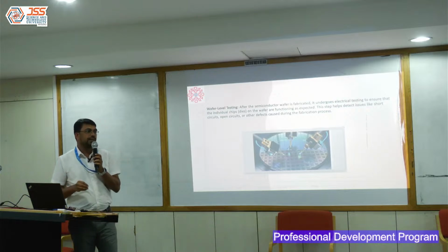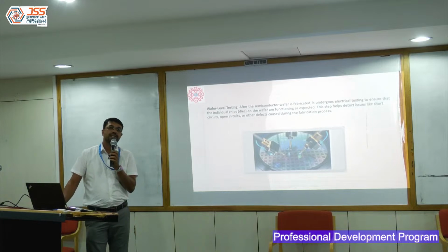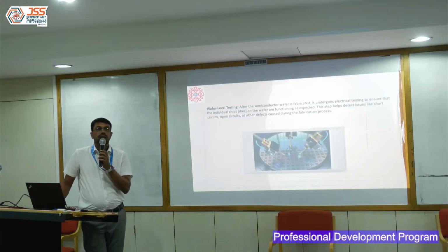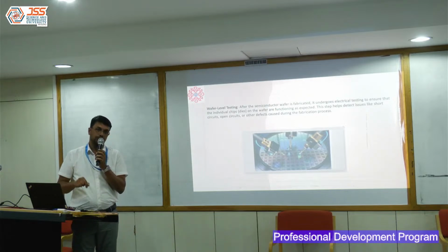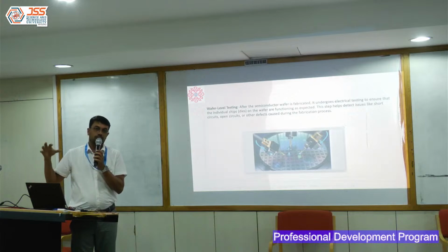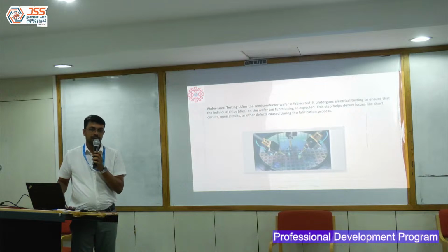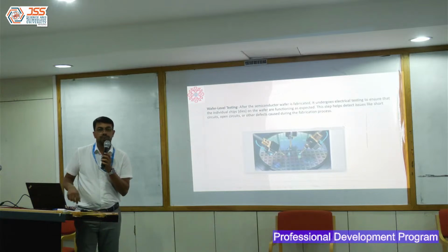For this analysis, there is a tool called Yield Insight from Mentor Graphics or Siemens. We use that tool and we do a yield analysis. That's where we try to pinpoint the exact node where there is a fault. When you have 80 pieces to analyze, if say 70 pieces have the fault at the same point, they go back and tune their fabrication process to reduce this. So the next wafer that they produce can give you a yield of say 30%. That's a 10% improvement. Again, they do this analysis. This is how the yield improves.